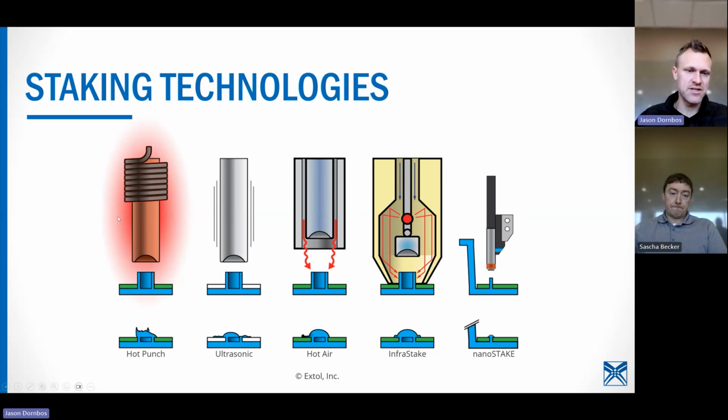In this technology, this entire punch is being heated to your operating temperature, 500 degrees Fahrenheit, maybe it's hotter than that, maybe it's a little colder, but it's being kept at an elevated temperature the whole time because it takes too long to heat this punch to that temperature. And then if you tried to cool it down between cycles, it wouldn't work. It would be too slow.